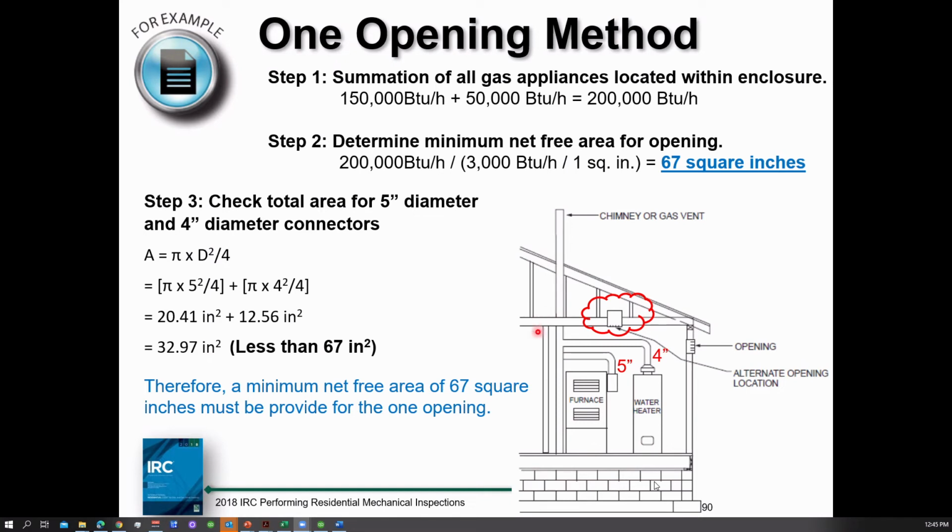Another thing I noticed too, where you indicated that there was louvers. I know throughout the country, sometimes they put louvers that you can close for the crawl spaces. We don't allow those here because people close them in our higher elevations here. Lower elevations, we don't bother with it, but they can close that off and they lose a great deal of their combustion air if they're pulling it from the crawl space.